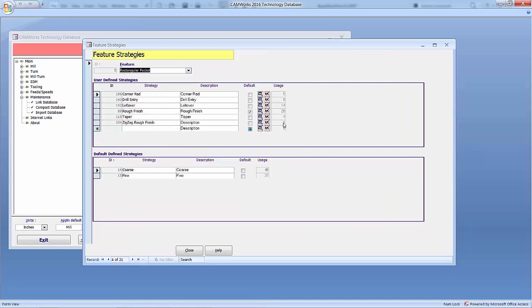It's only used once, one set of feature group conditions, the size, depth, material, and so on. It's only one place, whereas the rough finish where I base that strategy from happens 28 times. So I'm really losing out on the scope that this strategy can apply to because I have very, very few feature conditions relative to, say, the rough finish.